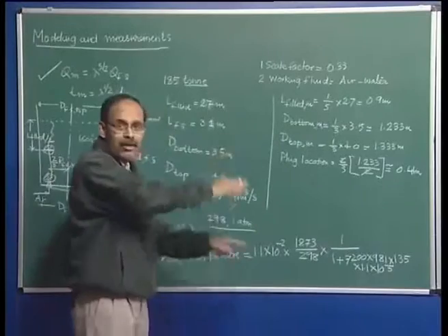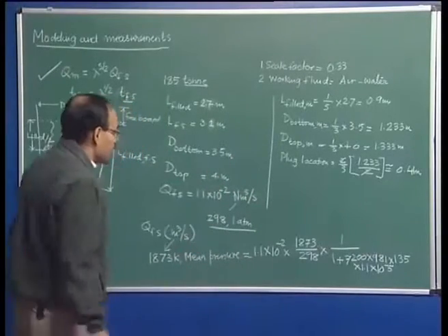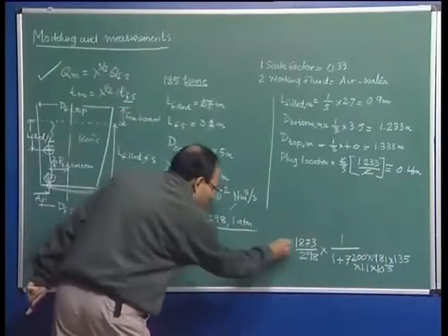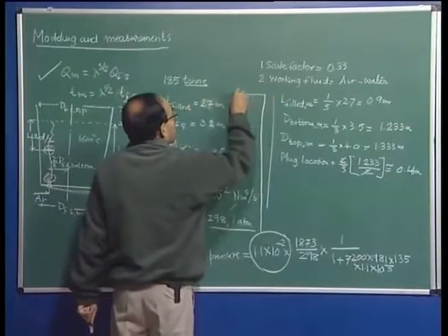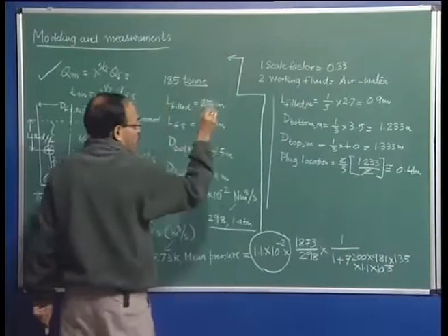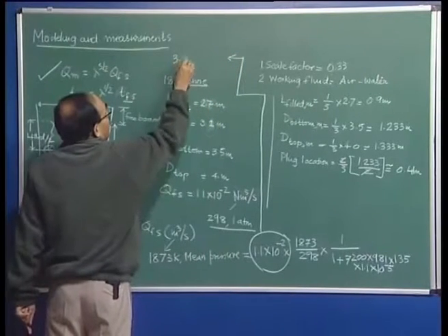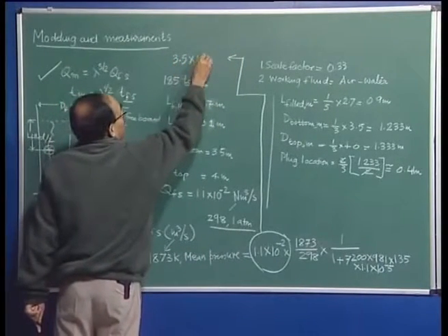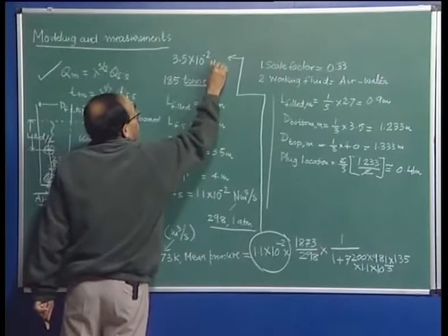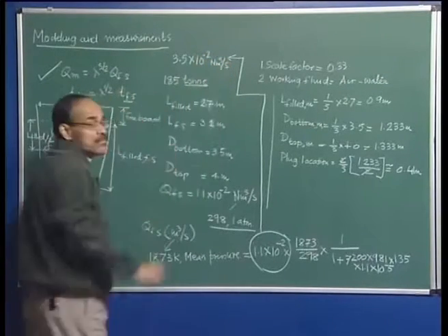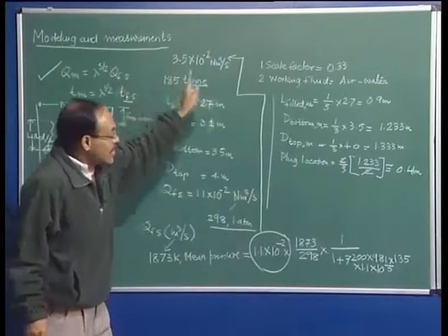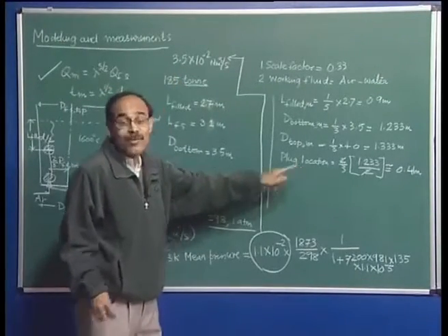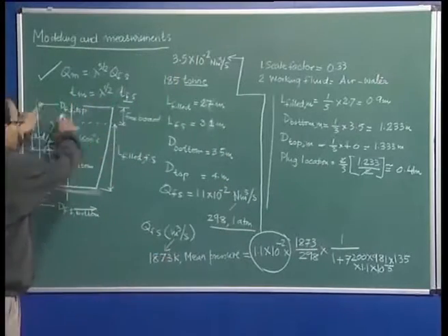So, the overall contribution of pressure and temperature is going to be, this gas flow rate will feel like approximately 3.5 times that gas flow rate. So, this gas flow rate needs to be scaled down in order to find out the model flow rate, because this is the actual flow rate experienced by molten steel.